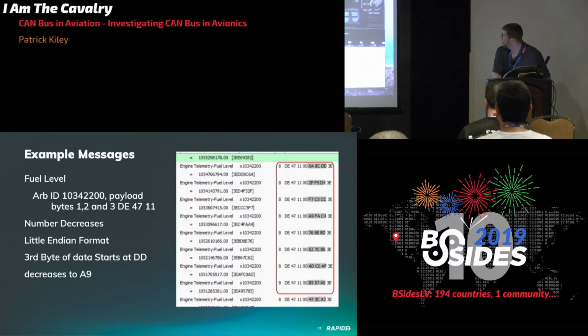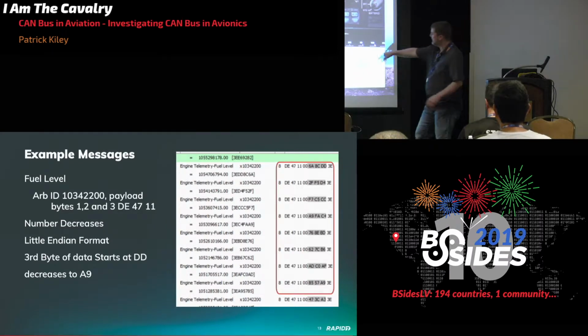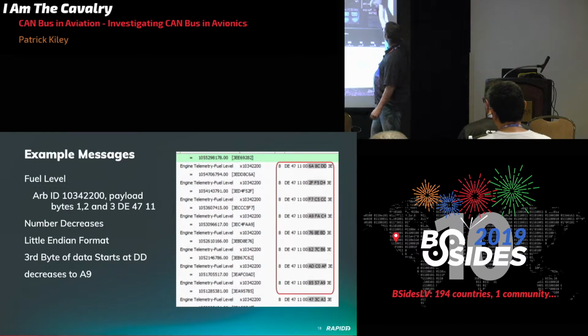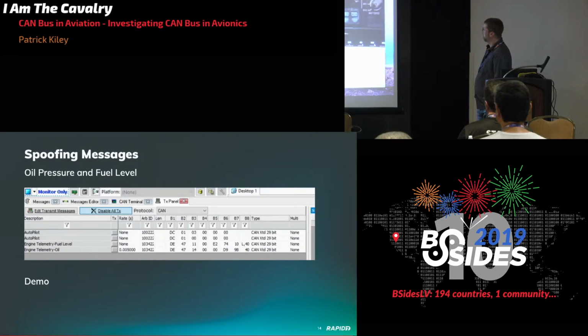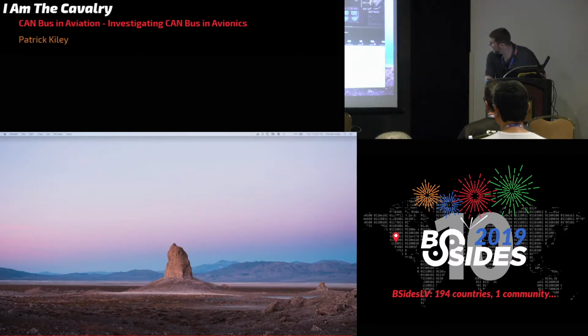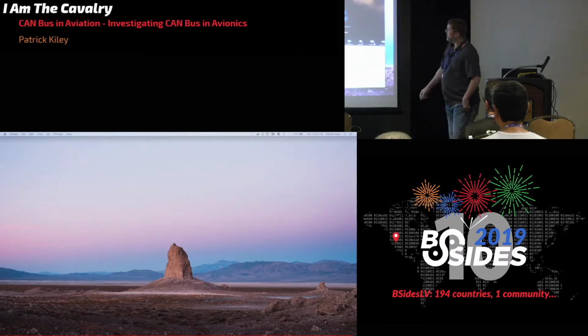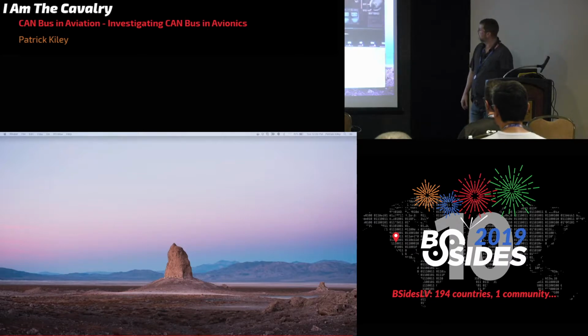Okay, so this is a close-up of my instrumentation kit, and you can see these are the 2 variable potentiometers I put in to control the oil pressure, because I didn't actually have an oil pressure sending unit. But it's the same thing. It's a resistance that changes, and you'll see what happens to the signals as it adjusts manually. You see both the fuel level and the oil pressure drop as I'm adjusting them down.